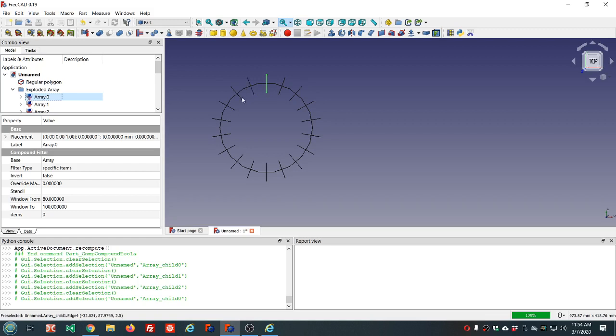Then this will be at 10, 20, 30, 40, 50, 60, 70, 80, 90 degrees, 100, 110, 120, 130, 140, 150, 160, 170, and we'll link back to this one. I'm going to make a clone of this last element so I can add it to the loft list of sections and rotate it 180 degrees, and hopefully this will make one solid. I've got my doubts. I think we're going to have a self-intersection issue, but we'll try it and see what happens.